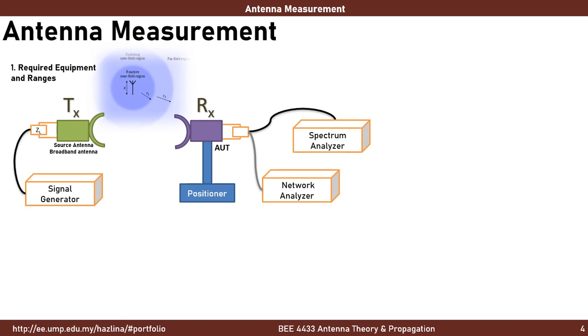Antenna operates steadily in its far-field region. These two units must be separated to comply with the far-field radiation range. Also, the measuring equipment must be placed at the appropriate height so as to avoid ground reflection errors.